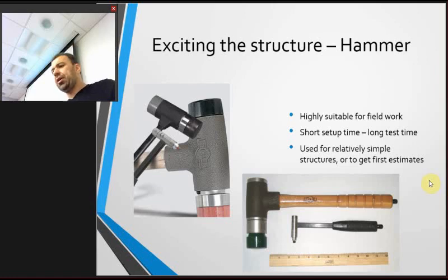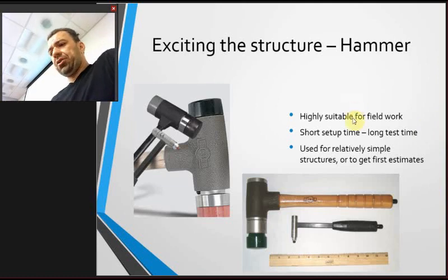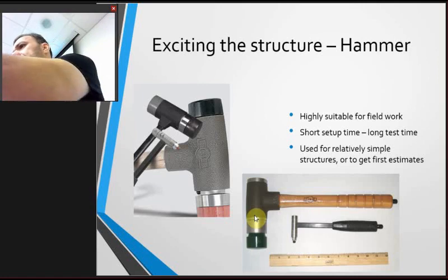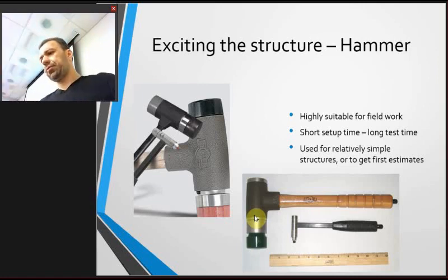Okay, let's talk about the excitation means. First of all, we have the modal hammer. They come in different sizes and shapes. Heavier hammers tend to excite bigger structures. What's so special about it is that we have a force sensor inside the head. So once we hit the structure, the excitation is recorded. I have an example here of a tiny one. Yeah, this is the hammer, the force sensor being here. So if you want to check it out afterwards, you can.